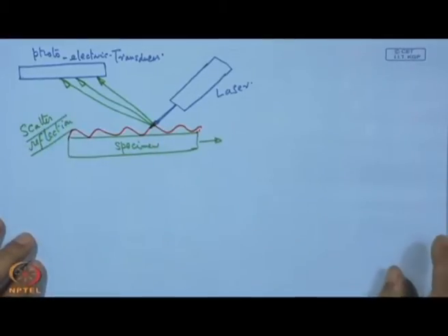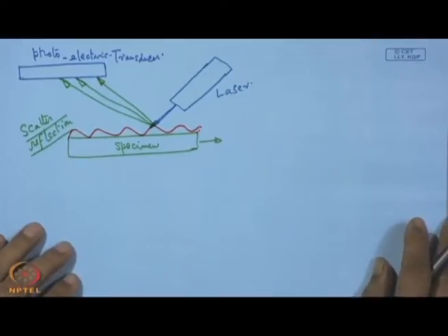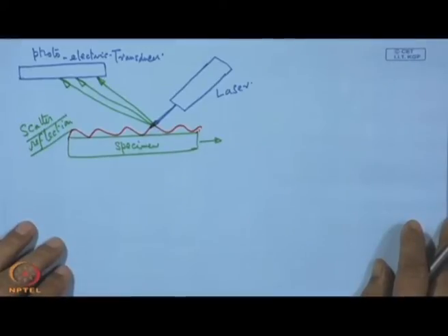So, this is another way, it is non-contact type. However, each system has its own merits and demerits. In this case, non-contact means that the radius of the stylus tip should not be a limitation. It is rather high speed operation, the process is faster.